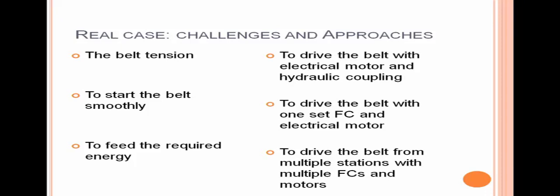For the questions and challenges I just mentioned, there are some practical ways in today's industry. One remedy or approach is to drive the belt conveyor using hydrocouplings between the electrical motor and the, let's say, load, which is our belt conveyor in this case. The hydrocouplings give us the capability to start our belt conveyor mechanically smooth, and this way the stress on our mechanical parts is reduced really significantly.